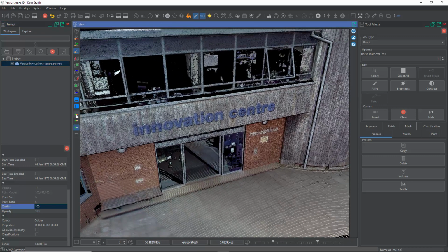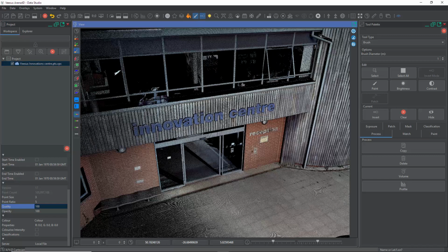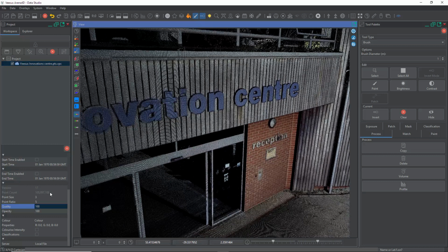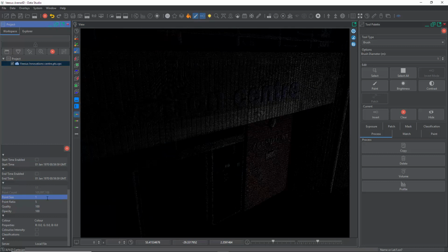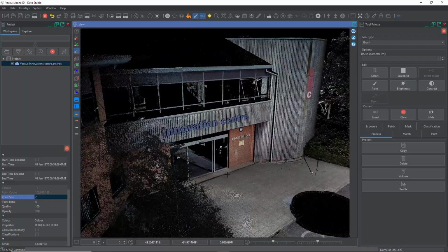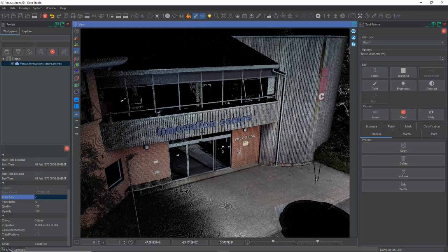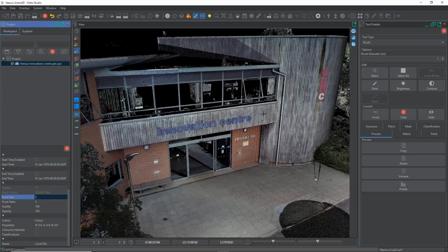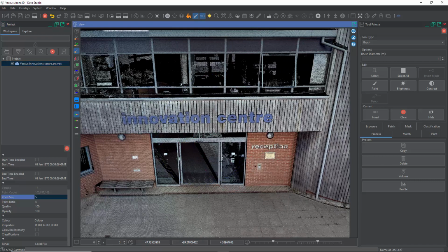If you have super sampling turned to the maximum, it will highlight the effect more obvious. If we had a point size of 1, the data can appear too see-through, not solid enough here. Filling and super sampling is dealt with in a separate video, and keys 1 to 5 will have been explained, but that's what they affect here, is the point size. So if I entered 5, you have very dense looking, very solid looking point cloud.